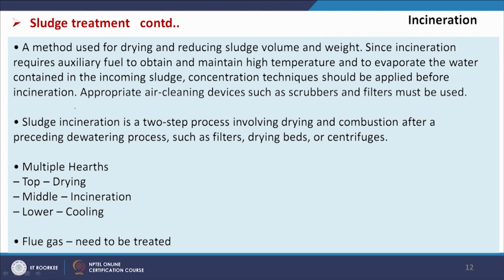So, appropriate air cleaning devices such as scrubbers and filters must be used. And sludge incineration is a two-step process involving drying and combustion after a preceding dewatering process such as filters, drying beds or centrifuges.